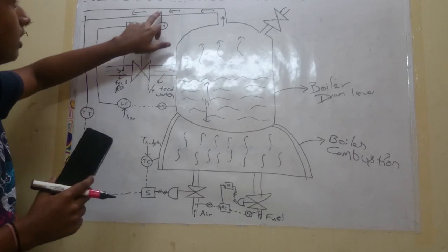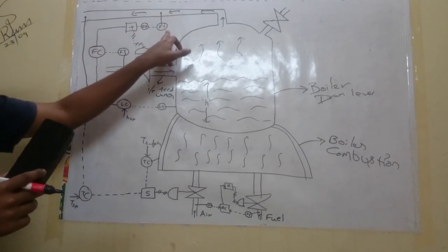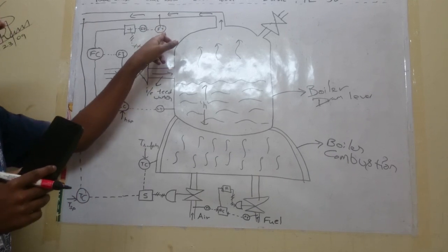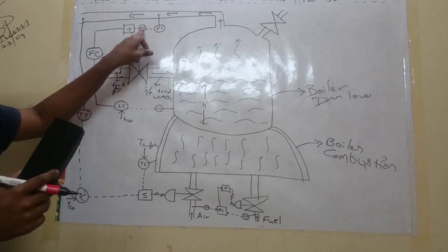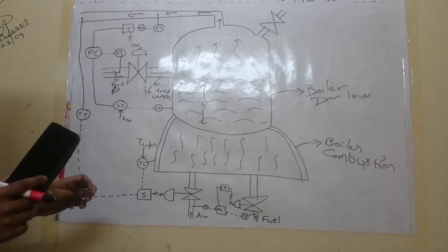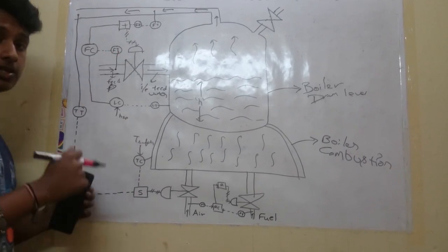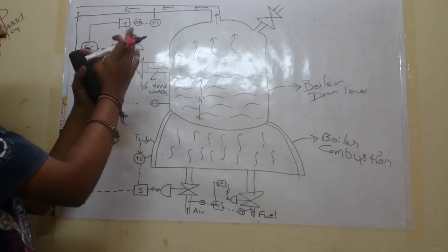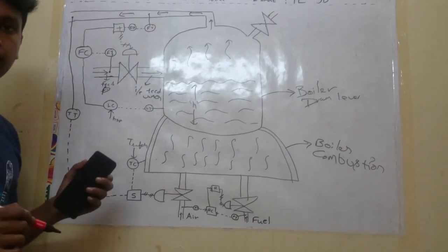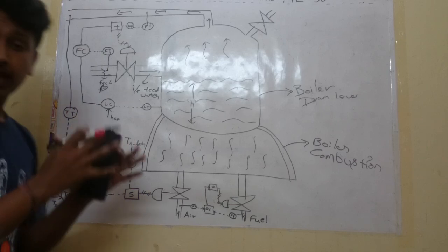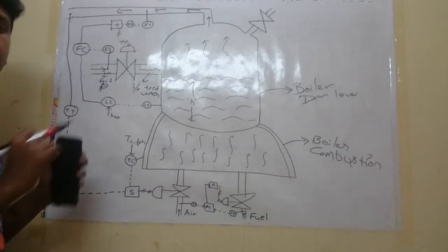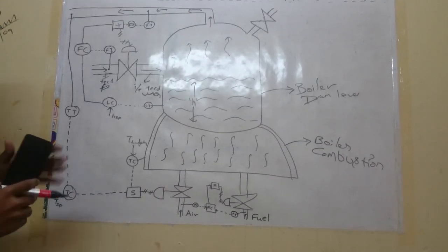of steam flow, like attaching a sensor, so it will measure the flow of output steam and transmit the value to the flow controller, and this is the feed forward. Why? Because it is a feed forward, it is a disturbance. So we are just reducing the disturbance directly by connecting to the flow controller, so that the settling time will be less and it will settle quickly, so we get a stable system. So this is the three elements.